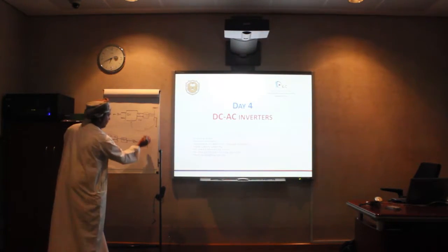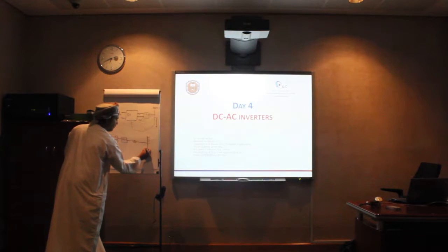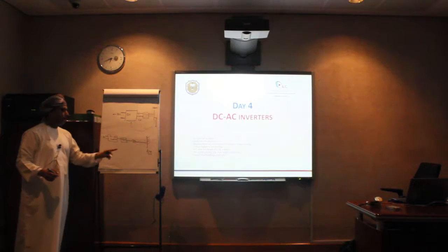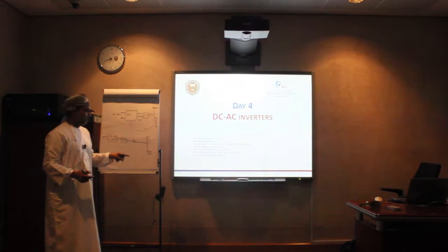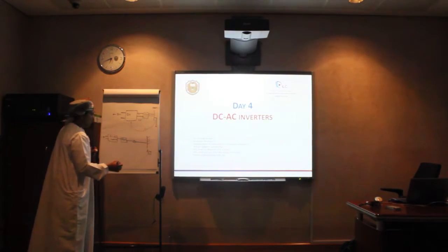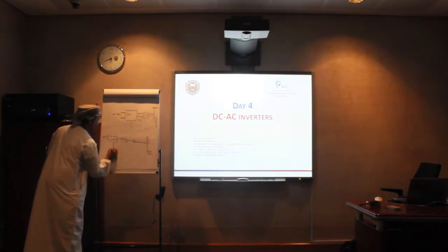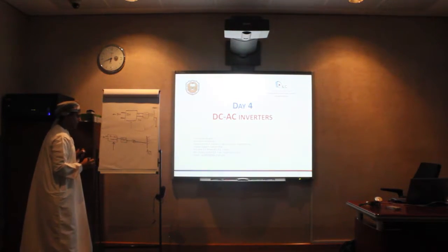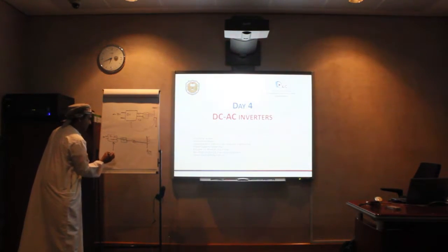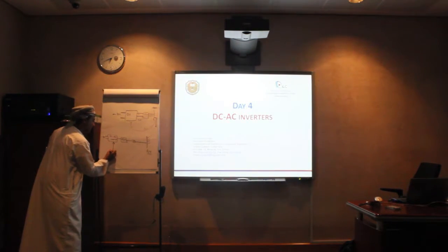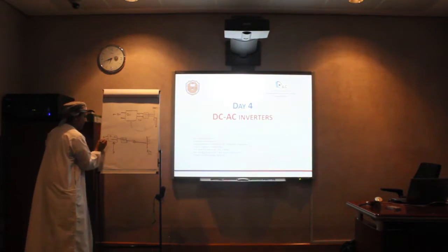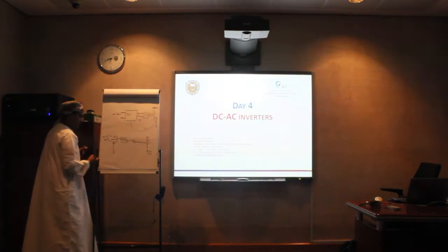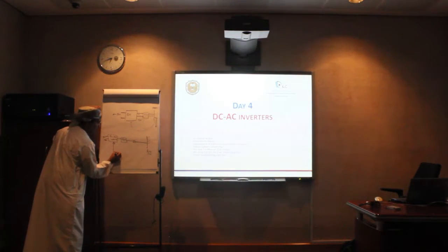So in this system, the frequency and the voltage are controlled by the grid. Therefore, in this case, my controller can be established by just controlling the power which should be injected from the DC side to the AC side, and also it could be reactive power.